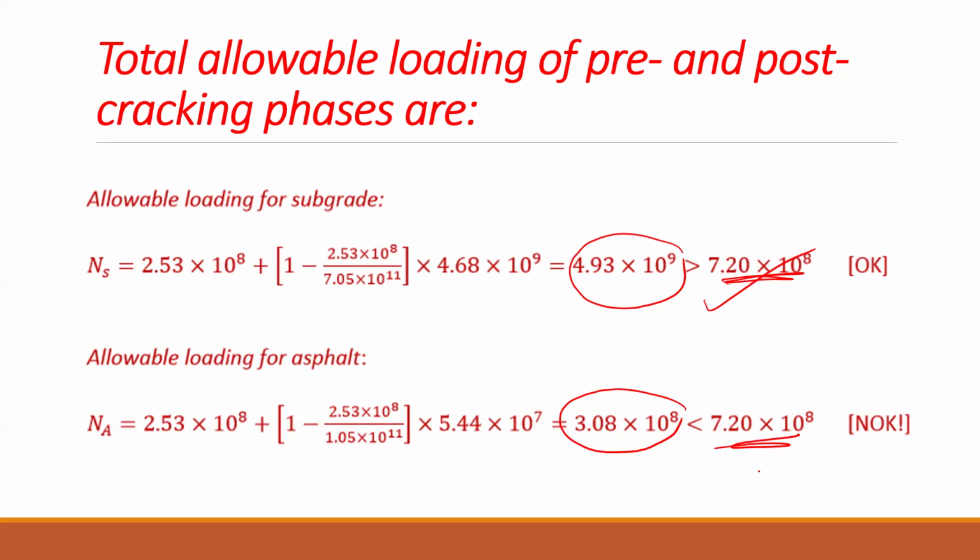In CIRCLY, you will find this kind of situation. In that case, what we can do is change the trial pavement. We can either change the thicknesses of different layers, or else we can add layers, maybe a granular layer or maybe another asphalt layer at the top. Likewise, we can change the thicknesses, the materials, the trial pavement. So we start with the trial pavement, not just without anything. We need to start with the trial pavement and we can proceed after that.